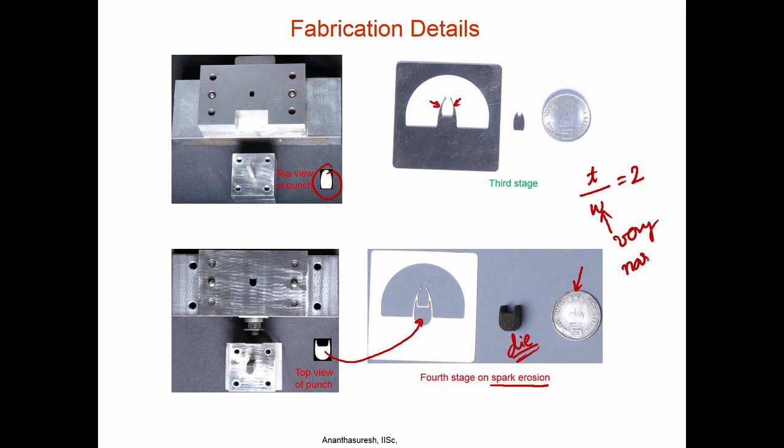So, if we can adapt both punching as well as sheet metal bending, we can actually make very interesting compliant mechanisms out of metal, which will be meso scale, and that is going to be competitive against lithography based MEMS sensors, accelerometers and gyroscopes and so forth. Those sensors are small, but when you put the electronics and package and everything, this is going to be meso scale, they are not going to be micro scale, they will be millimeter, centimeter scale. But the sensor element does not need to be small if there is a batch production technique such as punching.